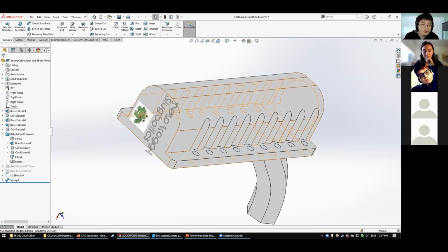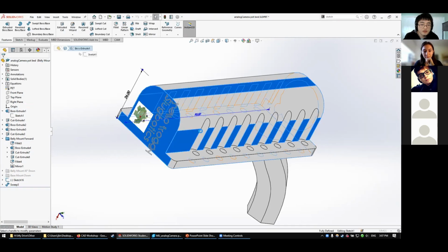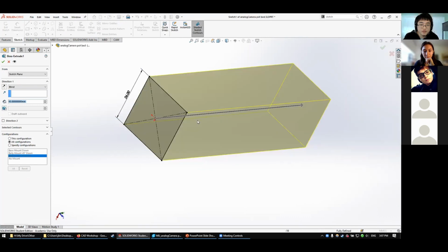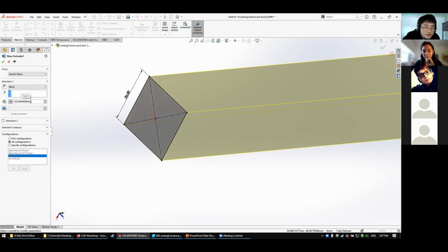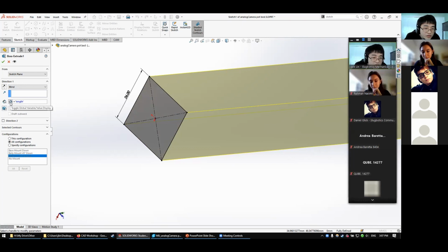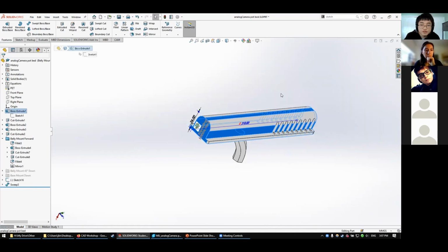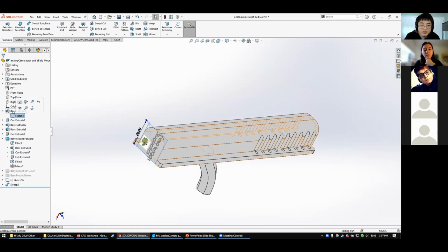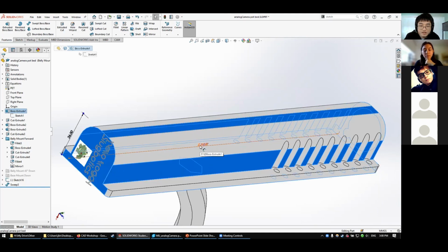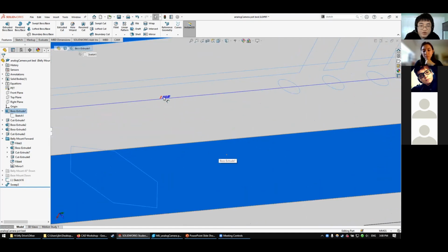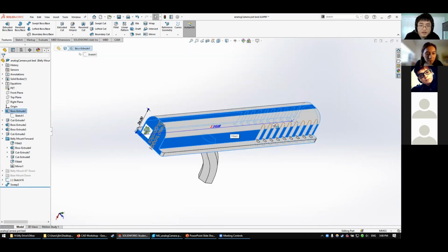And then I think when you do something here, so if I want this extrusion to be that, I say equals length. I think this way. Click on the global. Okay, so it should be length now. Okay, so it's 210 now. And notice when I click on it, this smart dimension I made now says equation sign, sigma 210. So that's how I know it's based on an equation that has variables in it.